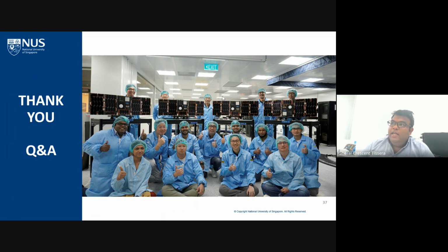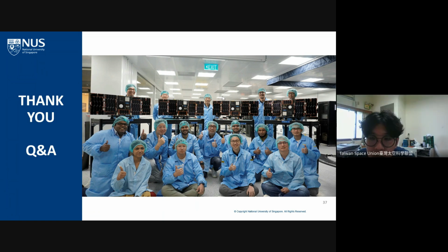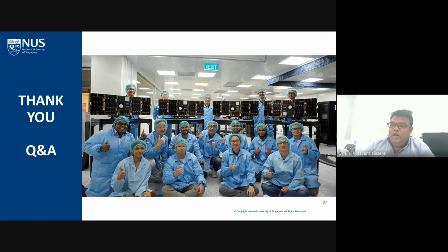So 12U and 16U satellites can still be deployed using a standard commercial off-the-shelf deployer. And these 12U and 16U are actually the biggest CubeSats that are available. So therefore, it is very attractive. But if the size is still not enough, then you are looking at 27U or 125U, where we will not be using a CubeSat deployer, but more of a ring-based adapter for the separation system.